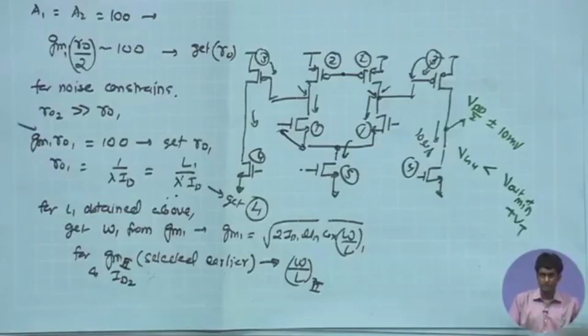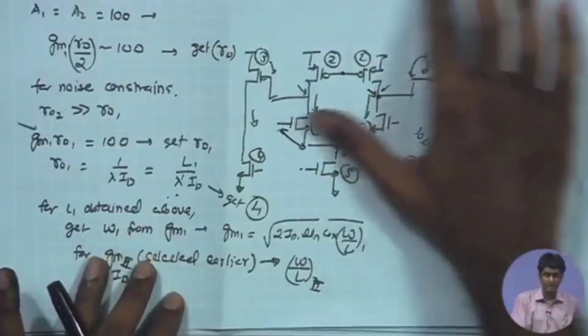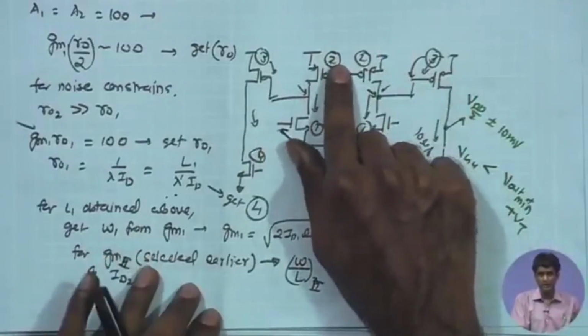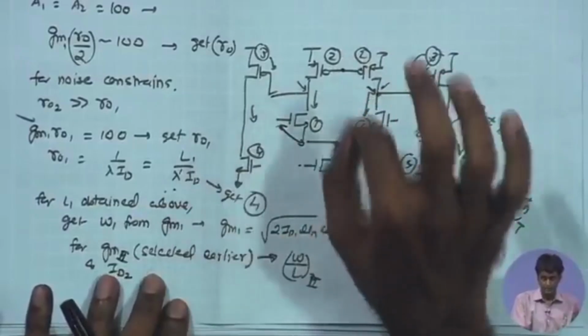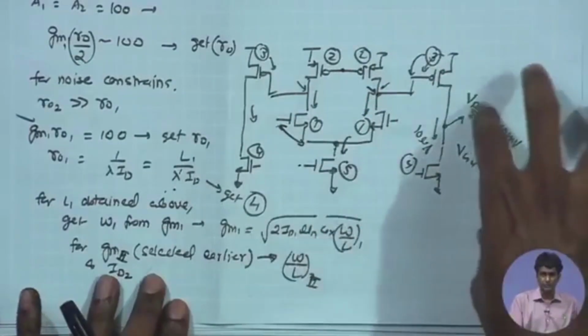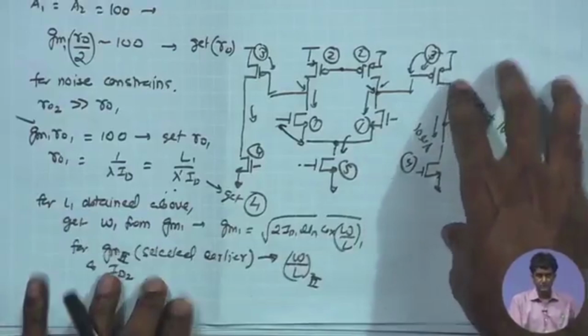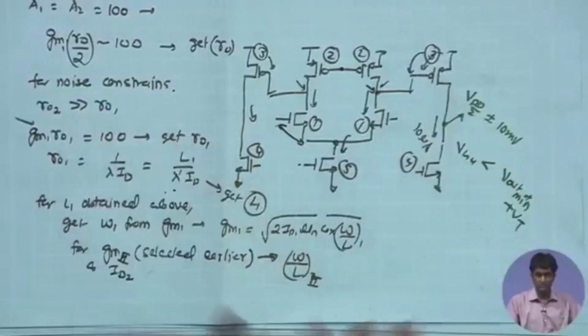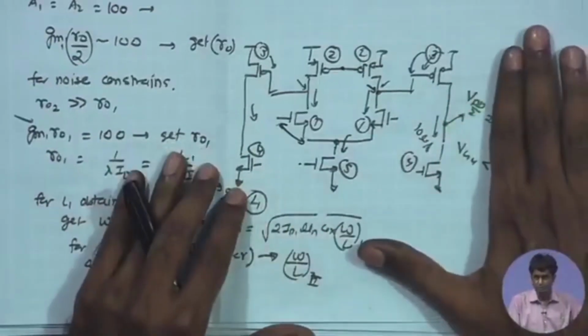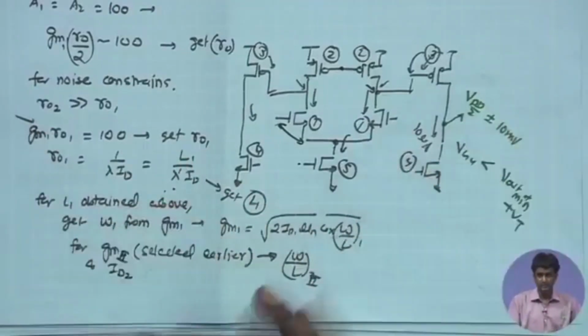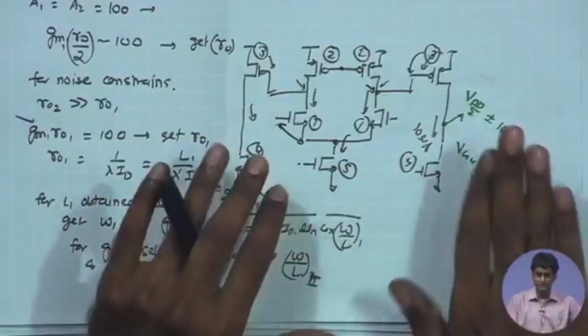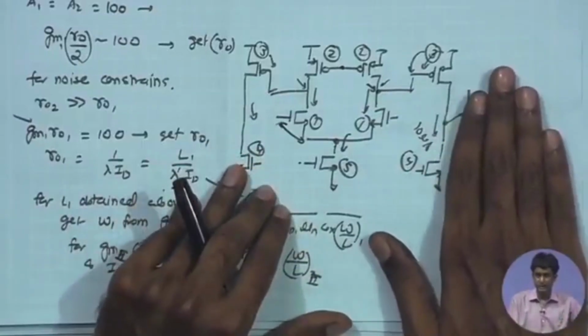Also the error amplifier output comes over here as a common mode, and whatever noise output is coming from the error amplifier is also appearing in common mode. So, the noise consideration for the fully differential operation will still be relatively constrained for the common mode feedback amplifier. Therefore, even for the front end amplifier, when we are discussing the sizing of the common mode feedback amplifier, the noise constraint will be relatively relaxed.